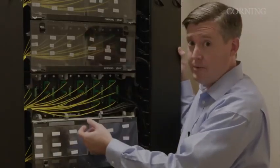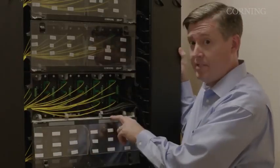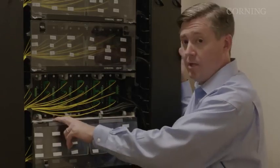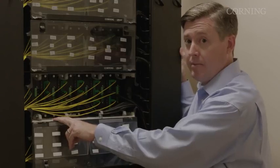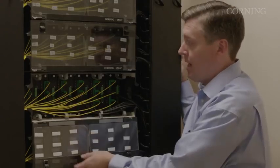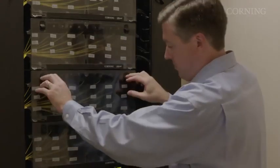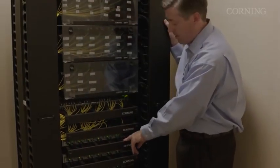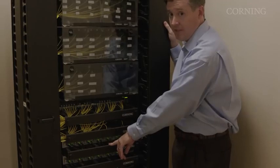The composite cables are coming in, terminating on the back of this housing. And now this housing is my patch point for both the fiber as well as the power, because remember, we're bringing composite cable into each of the rooms. The power is patching into the PSU. So this is where I'm getting my 100-watt circuits, which are feeding the ONTs.